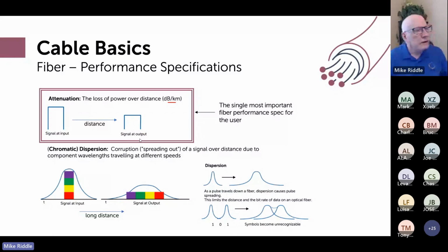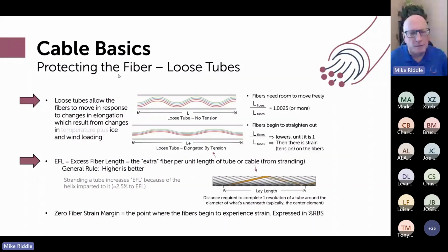So we talked about the fiber. Next up, loose tubes. So today, around the world for aerial cables, loose tube construction is what you see in 99.99% of cable. And in fact, in my considered opinion, it's the only type of construction that you should see in aerial cables. The aerial cable environment is demanding, temperature is changing, and so that will change cable elongation, not so much with ADSS, but some.